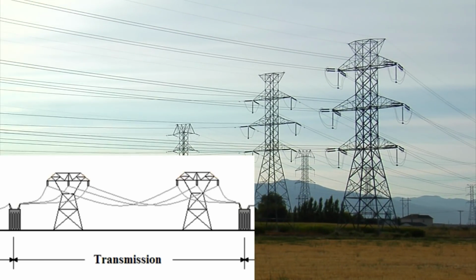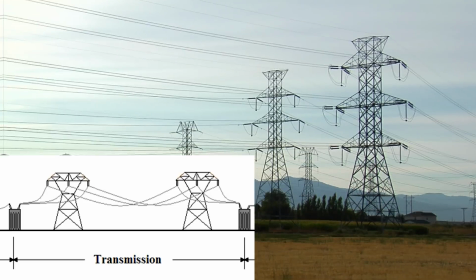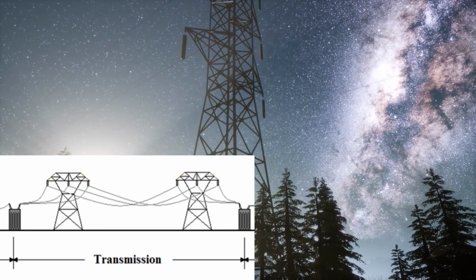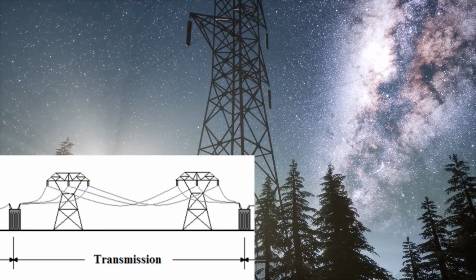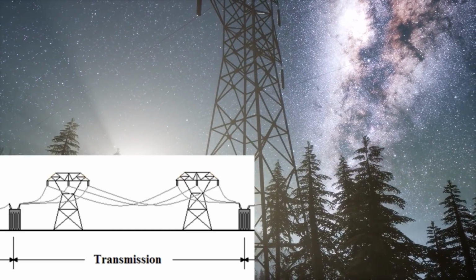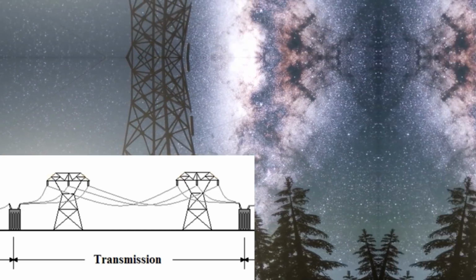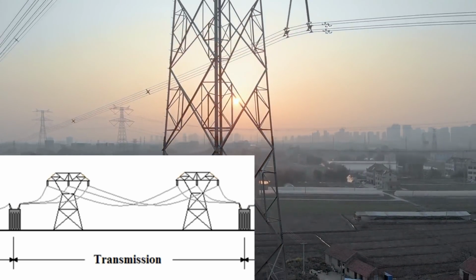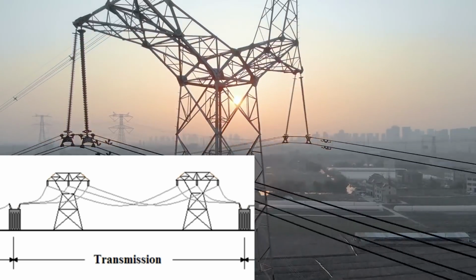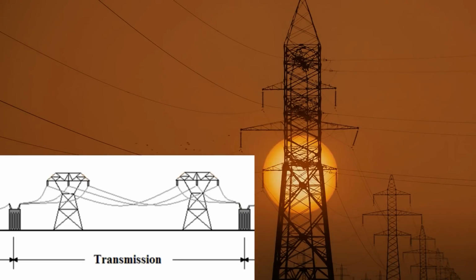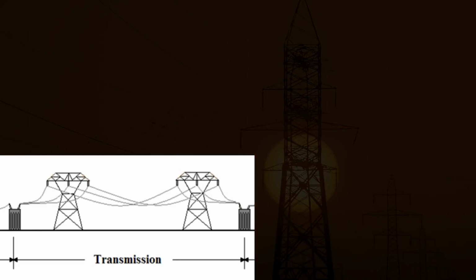Transmission includes lines, wires strung from insulator strings on towers or underground in special insulated containers, and substations, the points where several lines intersect and protection and control functions are implemented. With substations, there are transformers, breakers, protective devices, meters, and data transmitting and control systems. Protective devices protect the electrical components from unusual electrical disturbances that occur from time to time for many different reasons.